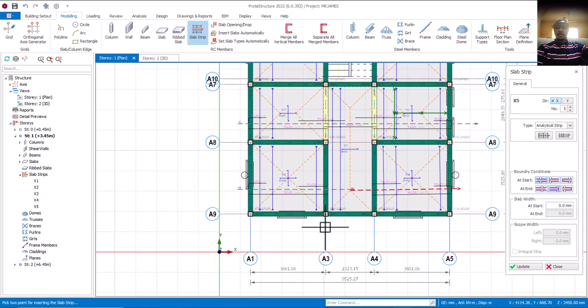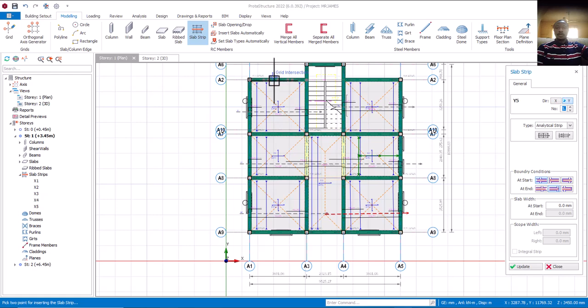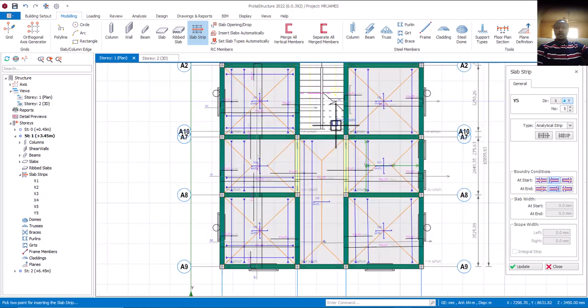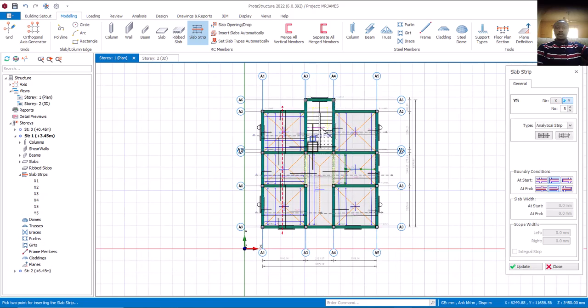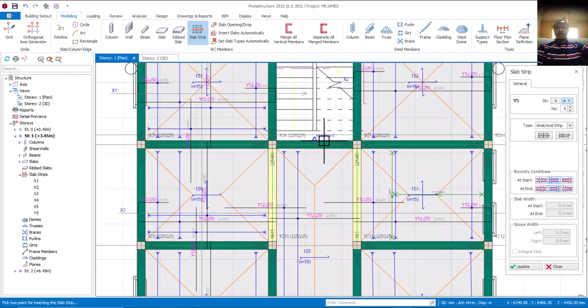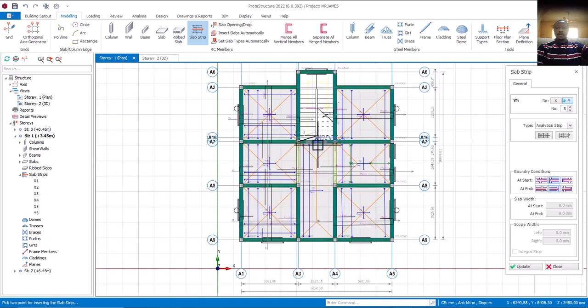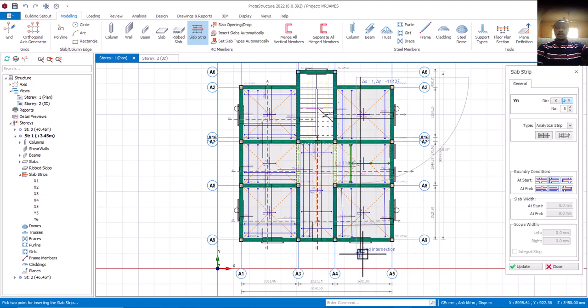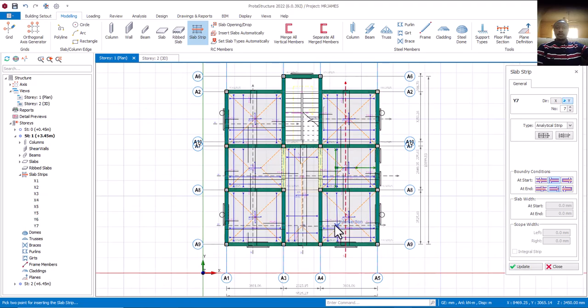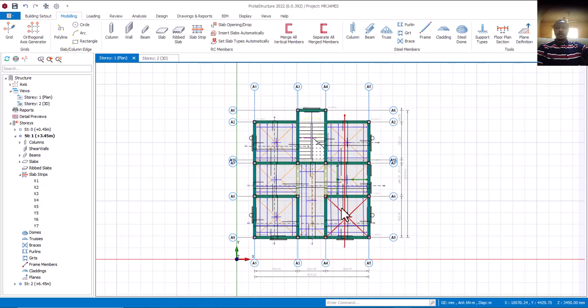So now that I've done it up to this place for the X direction, for another slab here I'll navigate to Y. Once I navigate to Y, I'll check from up like this, beam to beam. I'll come here, beam to beam, and click on this straight. Can you see it now? And from here I cannot be cutting through this opening. Is that okay? It will not work, so there must be slab. From here it's also beam to beam, and from here also beam to beam. Click. Can you see now? So we can now have our reinforcement for this slab.